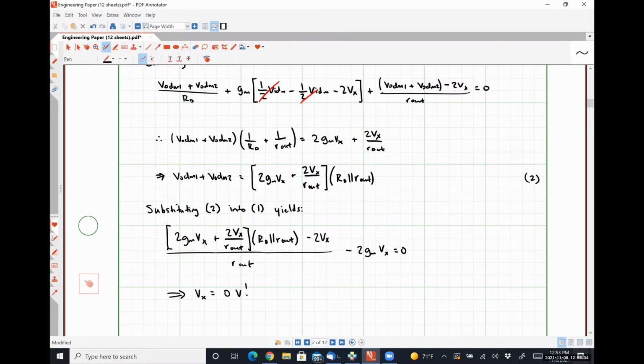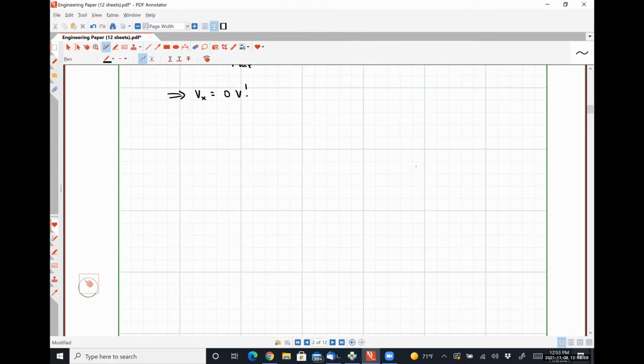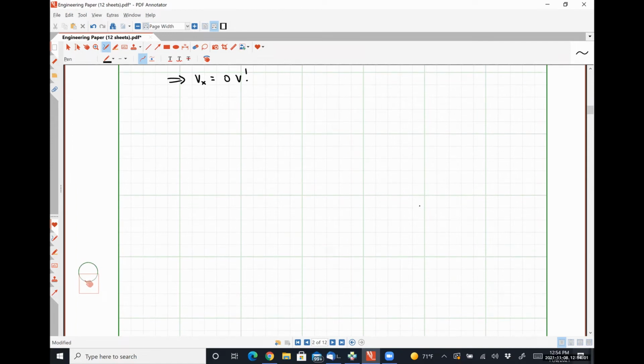So this means that even though we have a differential mode signal providing skewing currents in different directions, we wind up seeing that our source node for both of our transistors looks like an AC ground, which makes analyzing our circuit very easy, right? So with sources of both of our transistors tied to ground, we have something that looks like this.